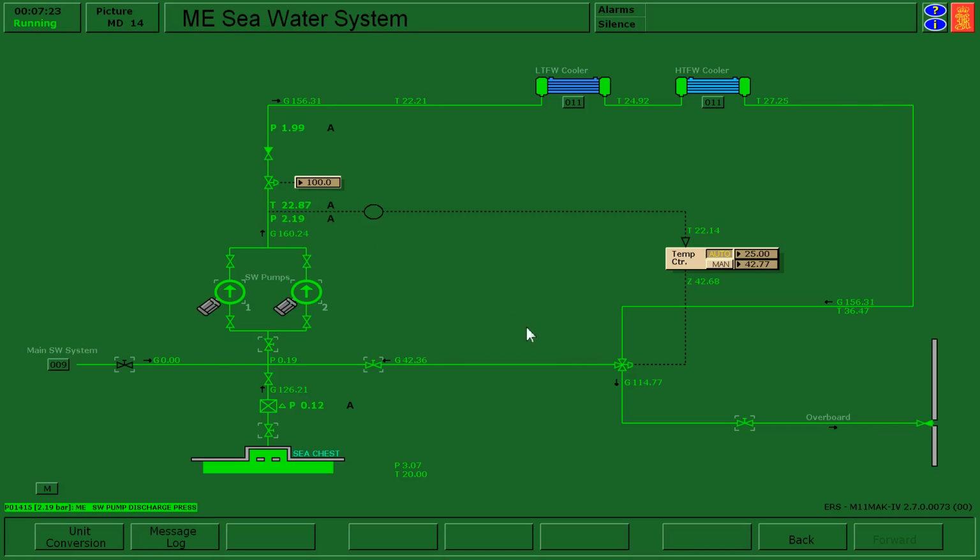Well, how does it go up? It goes up by sending more hot water into the system. The controls, as you can see, is this bottom number. And what that's telling me is the valve position. So if I looked at my valve here, I can see that it's about 42% open. About 40% open and continuously changing.